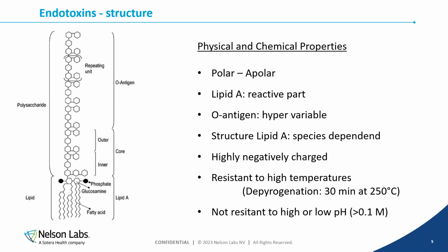And why is it so important to understand this? It is that they stick very well to positively charged surfaces like glass. So if you have pyrogens and you inject them into a glass vial, or you have an infusion bag, which has the same problem, they most probably will stick very strongly to the surface of the container.